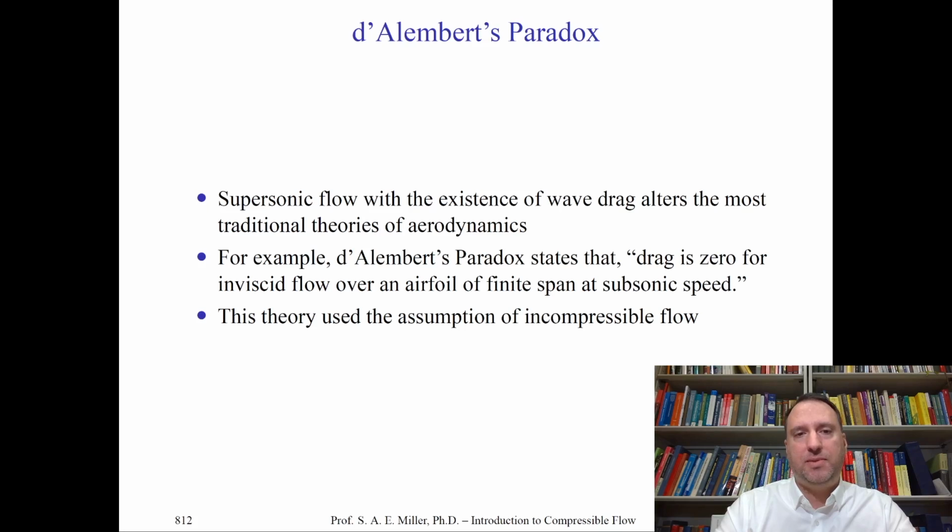Remember, D'Alembert's paradox states that, quote, drag is zero for inviscid flow over an airfoil of finite span at subsonic speed, end quote. Of course, this was found mathematically by D'Alembert and written in his famous treatise, and it was proven mathematically. But all objects actually do have drag, especially in viscous fluids, because they would slow down due to the aerodynamic forces. But mathematically, that did not agree with the present theory at the time.